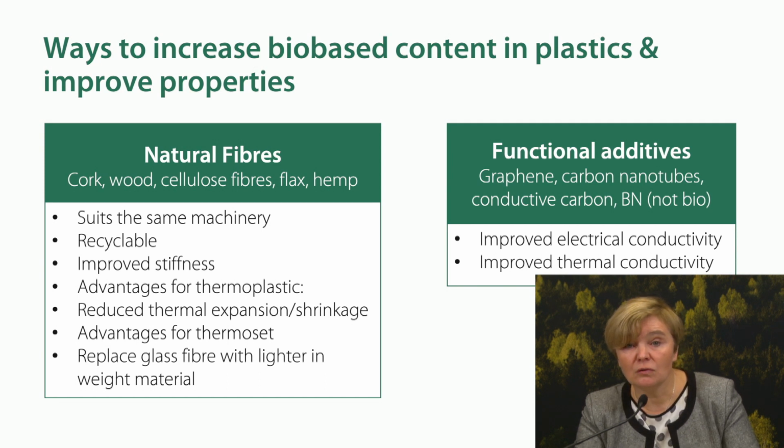Boron nitride could also be added to improve the thermal conductivity. It's an inorganic material, so you don't have it as a bio version, of course. There are also a lot of other components you would need to add. Maybe you want some different color, or UV stability agents, and always, when looking for those additives, you should look for the bio-based versions as a first choice.